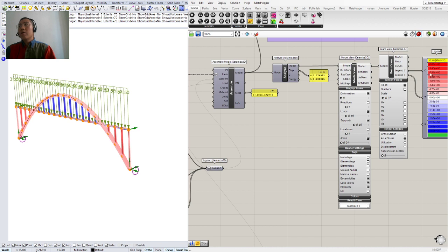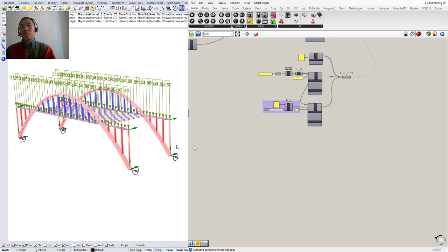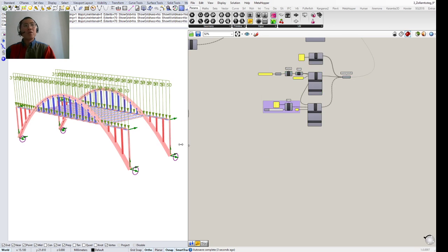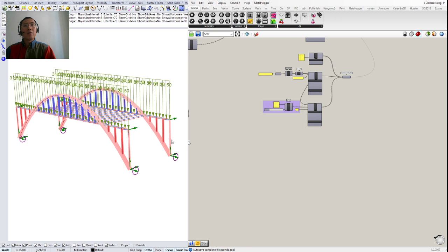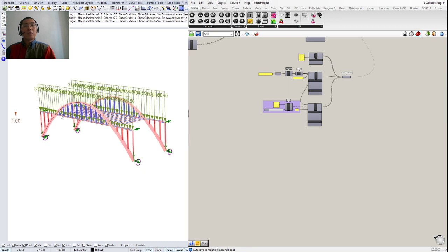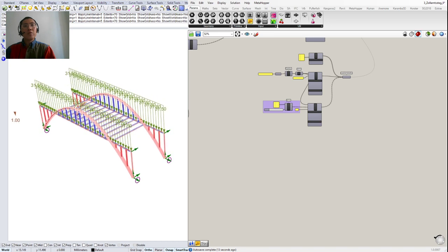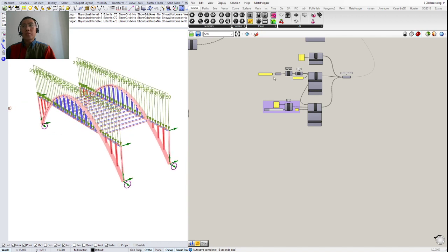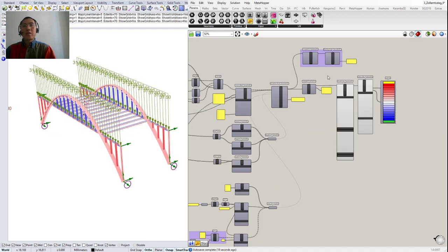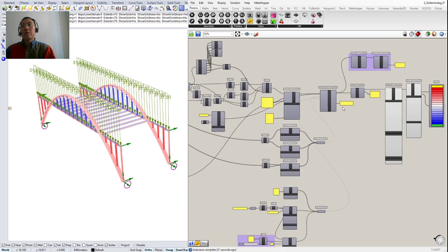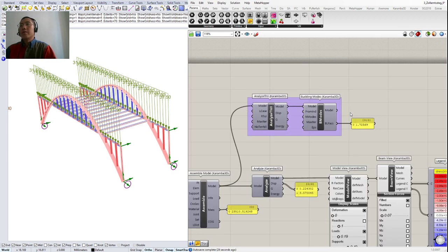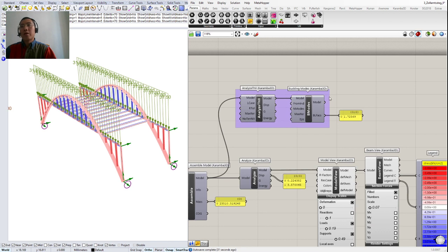So, when Clemens finished off last week, we were already in the 3D version, where he started to basically duplicate this frame across and then apply these horizontal members to connect the bridge. And what he did was an analysis in the second order theory, and he was also doing an analysis in the buckling modes,